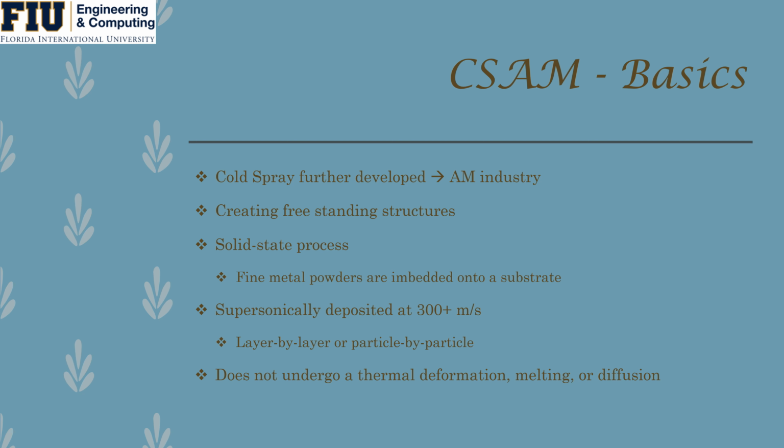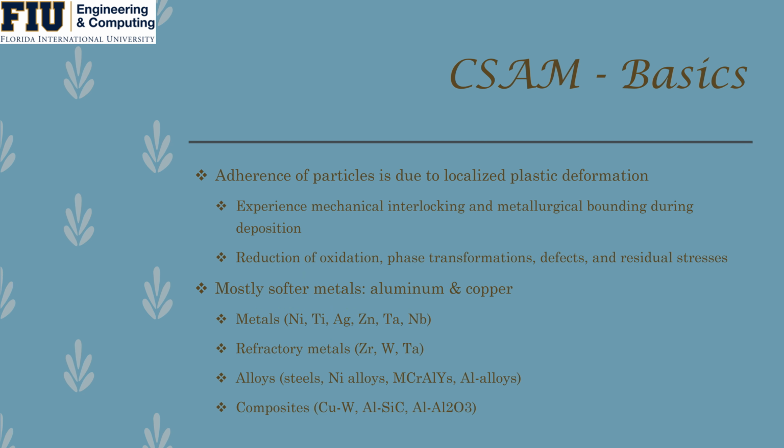This is done in a layer by layer, or we can call it particle by particle fashion, in which these particles do not undergo thermal deformation, melting, or diffusion, which is very beneficial for this technique itself. Since these particles do not melt together, the adhesion of particles is due to localized plastic deformation. This deformation allows for mechanical interlocking and metallurgical bonding during deposition. This overall aids in the reduction of oxidation, phase transformations, defects, and residual stresses in the overall part.